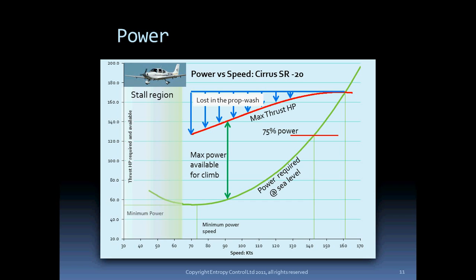I would suggest that when your engine quits, for the first little while at least, you don't even know where you're going or where you want to land, so it's important to sink as slowly as possible so you have time to think. Moreover, if you trim for 73 knots and plan your emergency glide and touchdown based on that, you have a little performance reserve in hand.